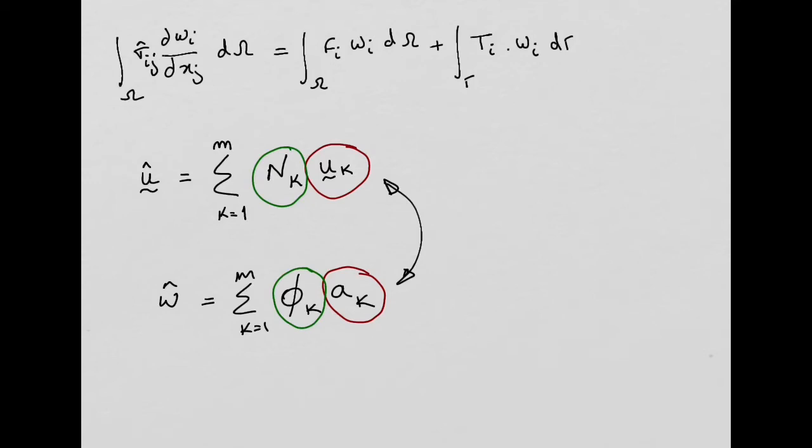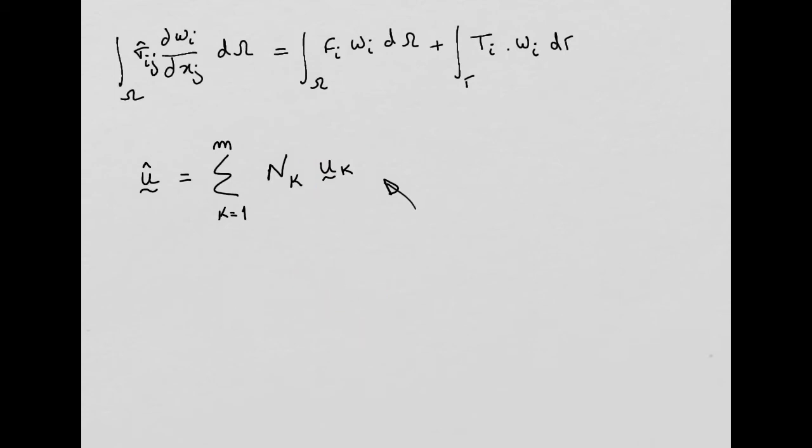So what I'm trying to say is that, like I said in previous sessions, the shape functions are defined a priori, right? So we know what the shape functions are. For the finite element analysis, they depend on the type of elements you are using. Okay? So this is the approximation function we are going to build. Now, I cannot just insert this approximation function directly on these integrals I have derived from the Green theorem. But it's quite easy to arrive.